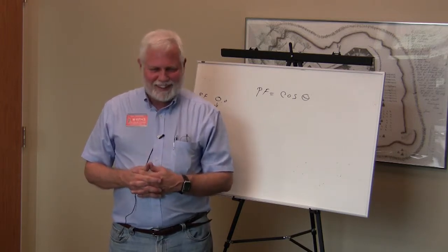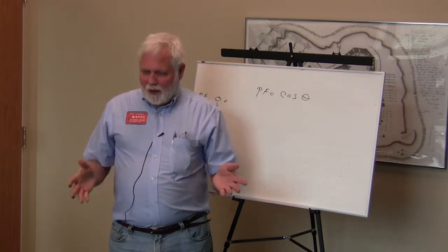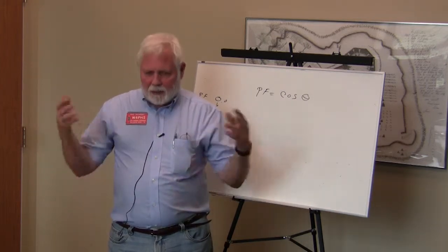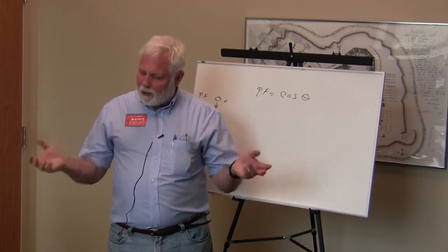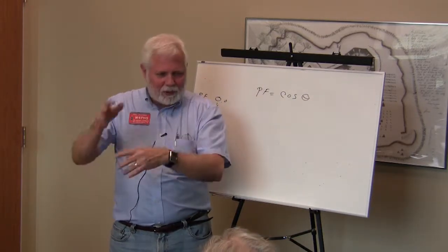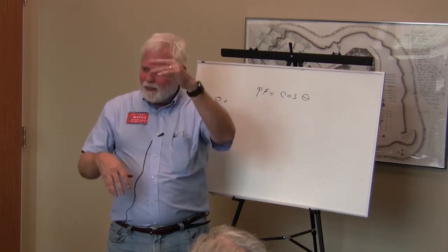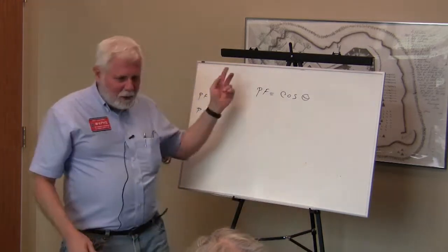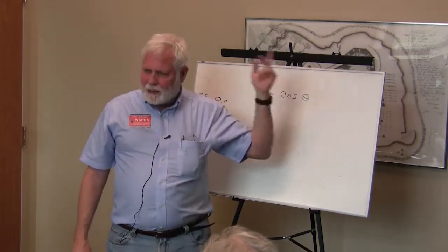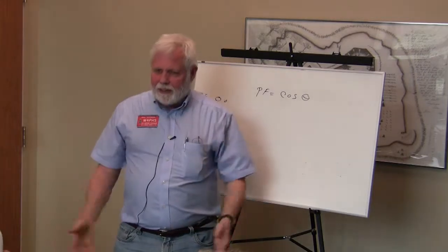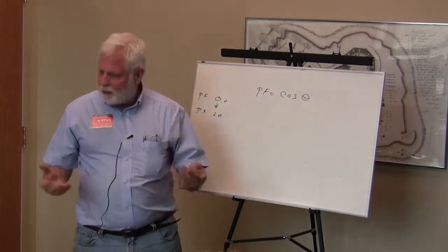Go for it. Okay. Well, think about it. Go over this stuff. When you get to these problems, pause and think about them a little bit. Think about that 45 degrees. Is it greater than 45 degrees? Is it inductive or capacitive? Positive or negative angles? Go back and look at Eli the Iceman, figure out leading and lagging. And I think once you begin to use these things, it's going to become pretty simple to you.